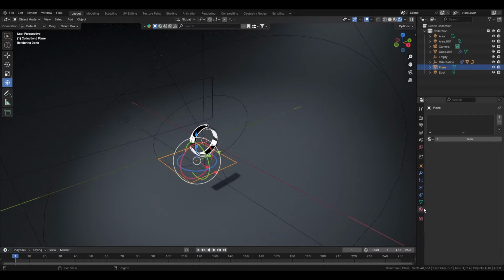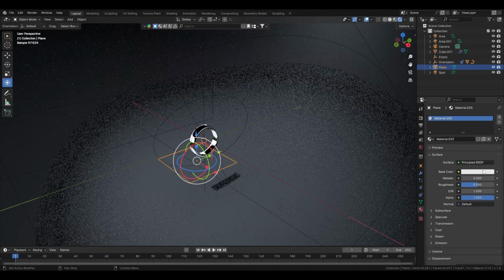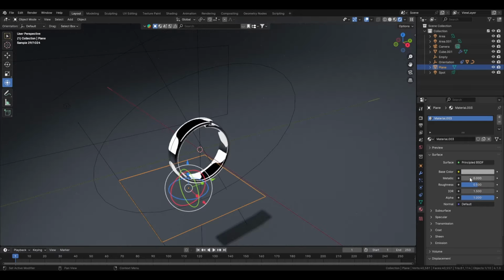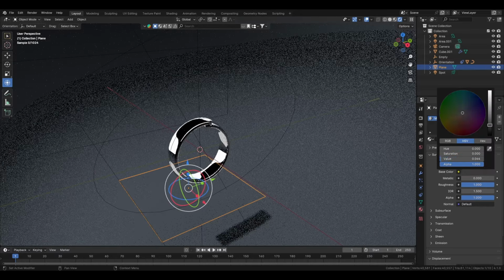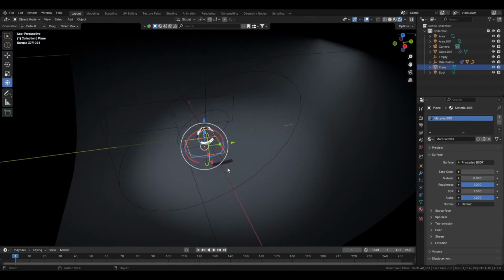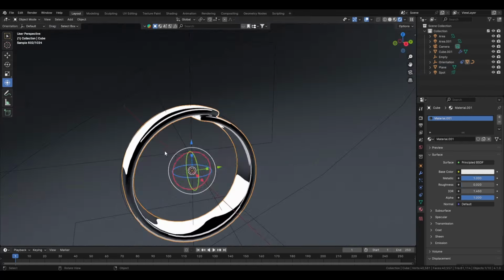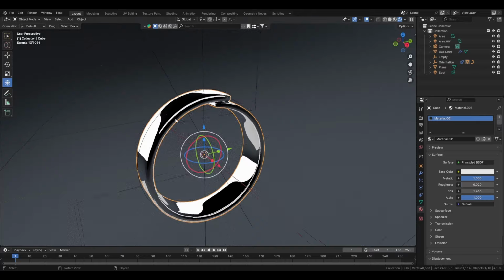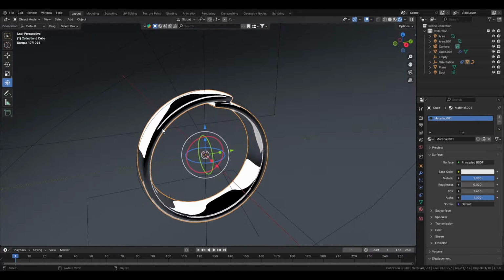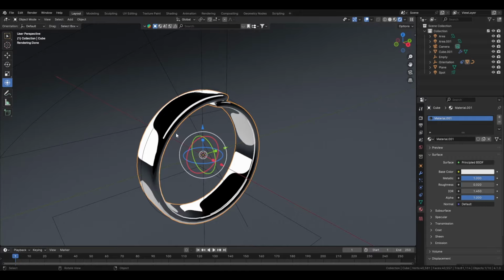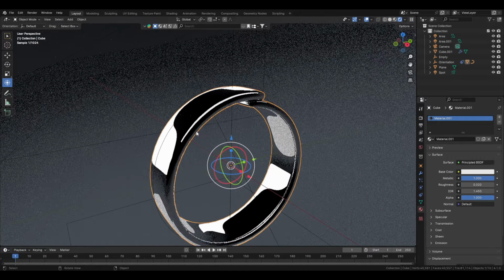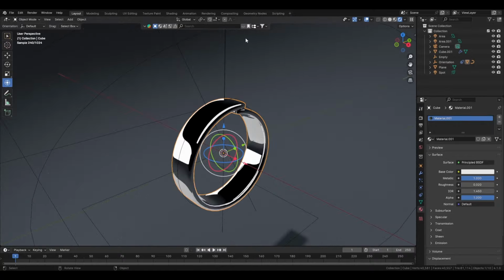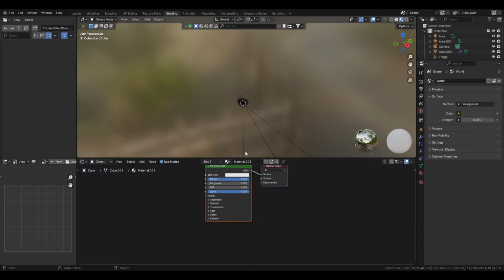And if it's too reflective, actually create a material, and you can always put a plane which is darker with the base color and rougher, like this. And a last trick regarding the ring is that we have perfect reflections of the light here, but in reality everything which is made would have some impurities, and this would probably be casted and then polished. So you can add this sort of impurities in the shader by going into your shader